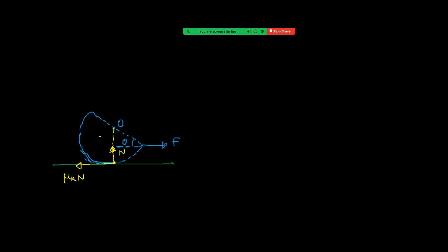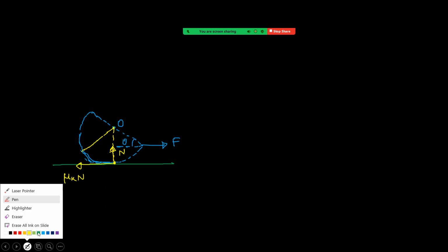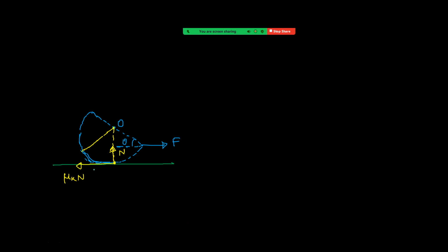Okay. Next, let us draw the normal for this base. And you can take here mg. Mg will be passing through the center of mass, or you can say center of gravity of the hemisphere. And the center of gravity is at a distance 3r by 8. Okay. We can take somewhere here the center of gravity, mg vertically downwards.